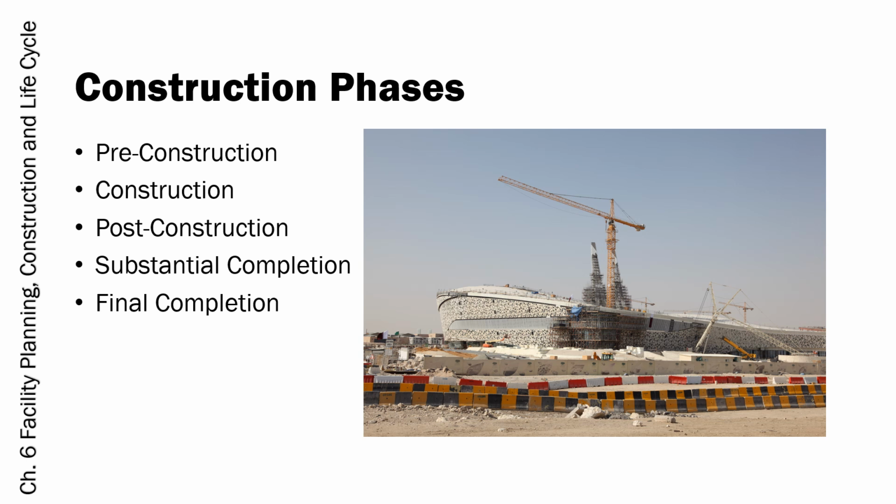Post-construction phase begins once the building is nearly finished and includes tasks required to prepare the building for occupancy and handover. Activities during this phase typically include final inspections and testing of building systems, ensuring that all punch list items, remaining minor tasks or issues, are completed, finalizing documentation such as warranties, operation manuals, and maintenance plans, owner training on how to use the building systems and equipment, and handover of the building to the owner.